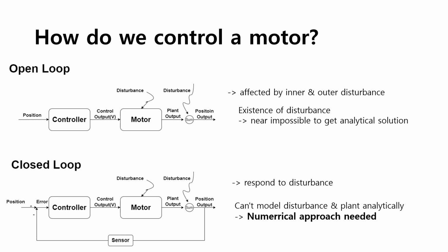We can represent this as a block diagram again, as shown in the bottom image. This is a closed loop control block diagram. We can see that the output of the motor is compared to its desired value, and the voltage is supplied according to the difference between the two. The difference between the output and the desired position is the error, and the voltage is actually another function, with the error as input and the voltage as output. We call this function a controller because this is what controls our input, which in turn affects our output.